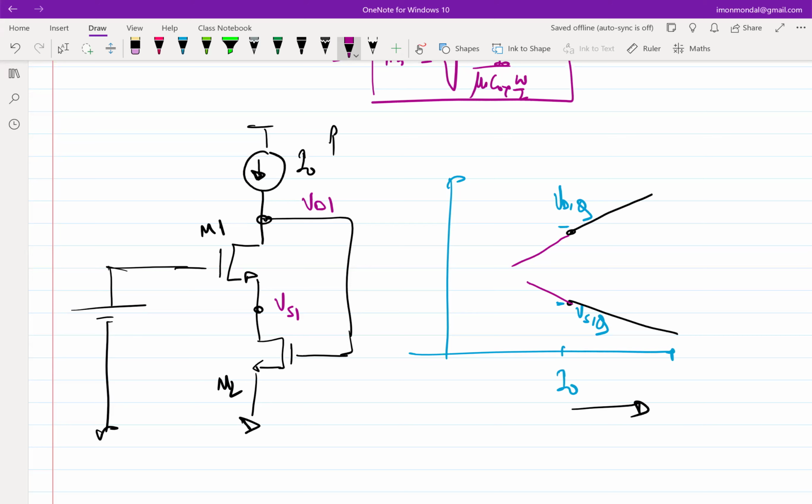How much margin you want depends upon those things, right? How much input swing you are processing and all those things. So if there is an input connected somewhere, then you have to figure out how much each voltage can change, and under the condition that the input has changed maximum from its quiescent state, you have to then bias it in such a way that all transistors remain in saturation. Okay, that's essentially the mantra for going about any circuit design.